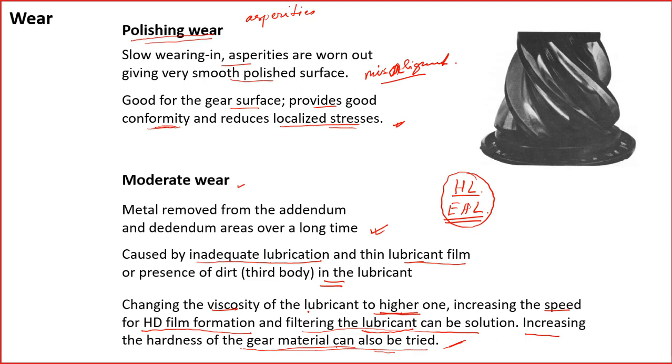Hello, sir. Sir, in moderate wear we are relying on hydrodynamic lubrication. So, sir, we have a constraint now. We have to make a closed chamber in which we put the gear and continuously circulate lubricant. So we cannot use it in many cases, sir.